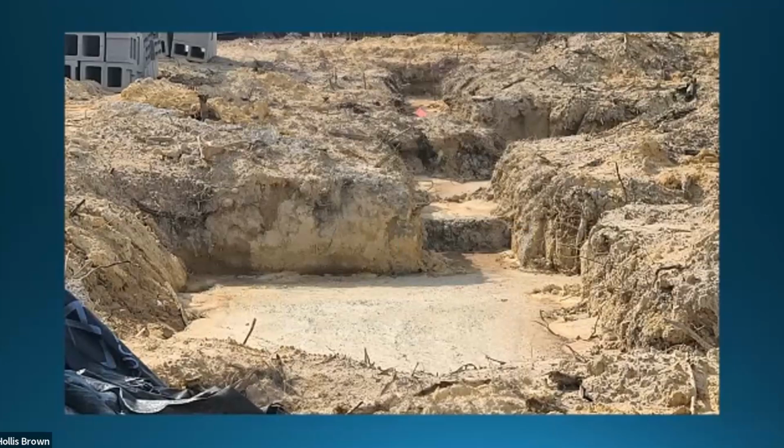The unfortunate part about that is, when you do these PSI tests and you send that cylinder off to the lab, they're going to hydrate that cylinder for a few days before they test it. So if that cylinder is hydrated before it's tested and the concrete in the field is not cured, what's the cylinder telling you about that concrete out in the field? Yeah, it's basically like shocking a well. It doesn't really tell you anything. The well still could have a problem.